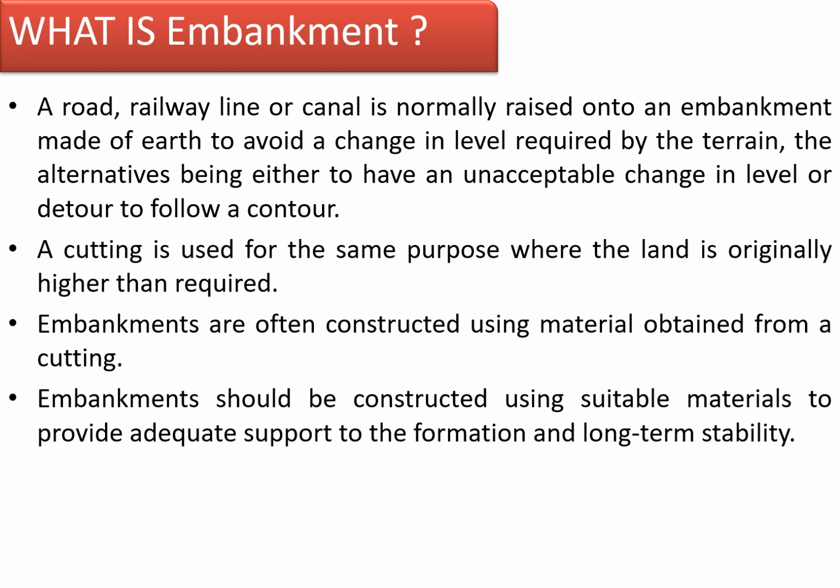By definition, a road, railway line or a canal is normally raised onto an embankment made of earth to avoid a change in level required by the terrain. The alternatives being either to have an unacceptable change in level or a detour to follow a contour. A cutting is used for the same purpose where the land is originally higher than required. Embankments are often constructed using materials obtained from the cutting if found suitable for the purpose.